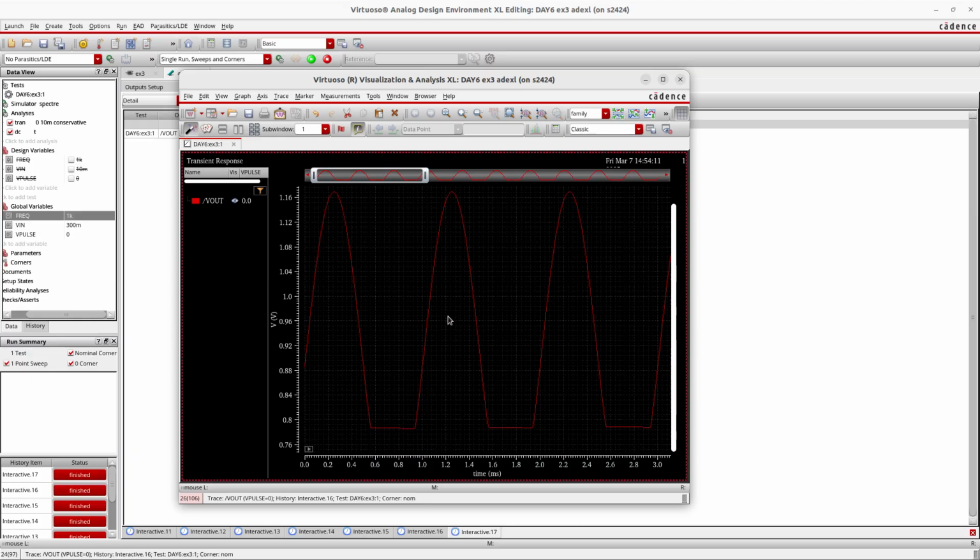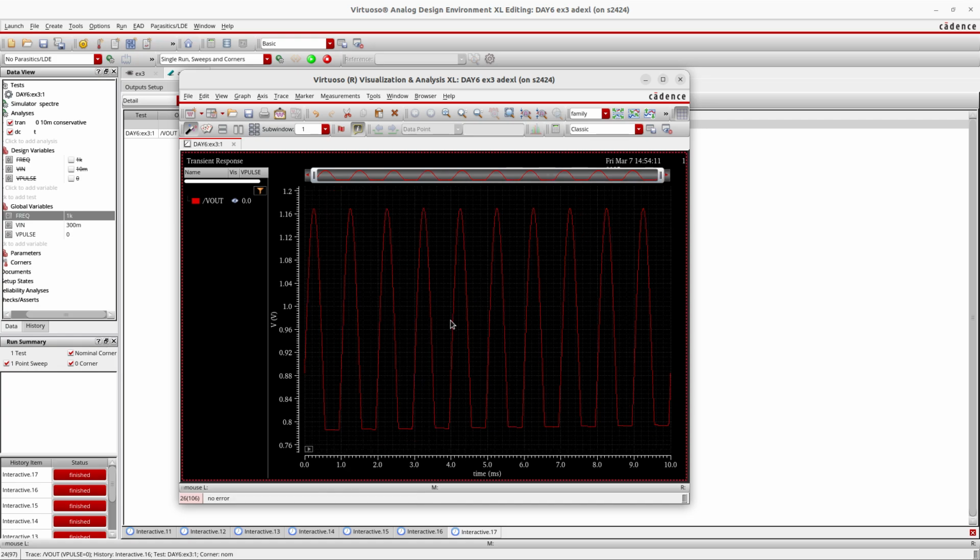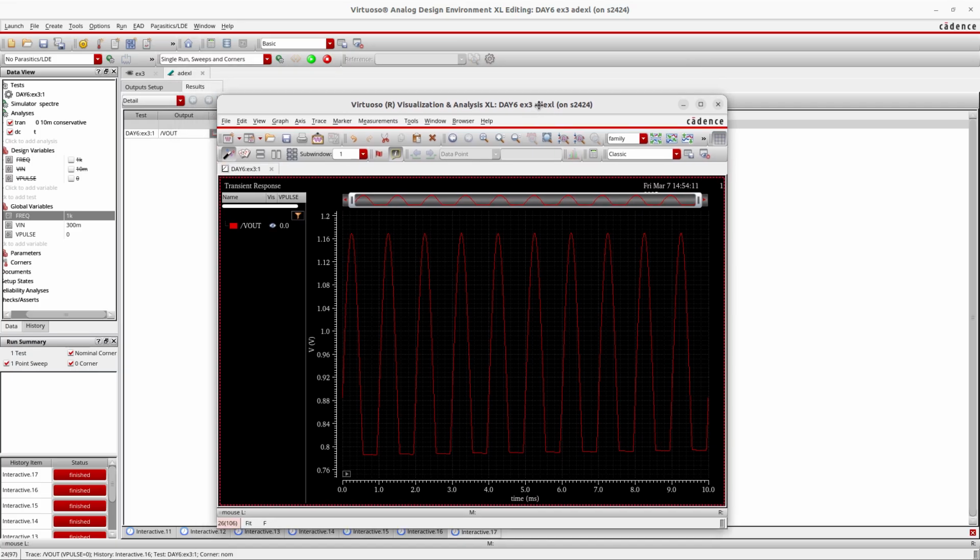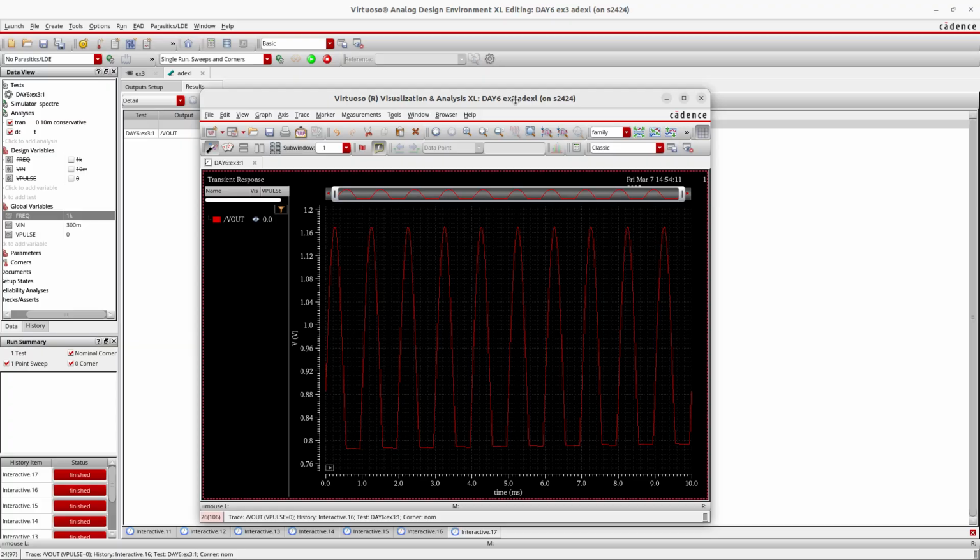And this is very important because sometimes we might think that the strong nonlinearities, the clipping, distortion happens only close to VDD and ground, but that is actually not true. If we have designed it wrong, if we have dimensioned the biasing of the last stage wrongly, the signal will just clip at any voltage. So this is a good example.